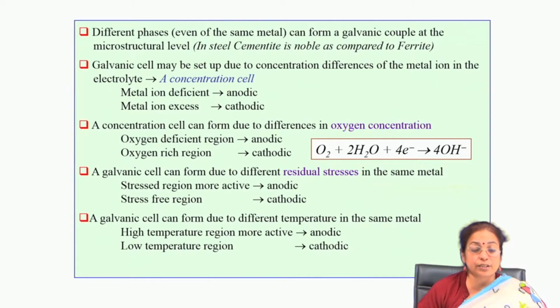For example, in case of pitting corrosion, the differential aeration cell formation is there because of oxygen concentration difference, which is nothing but a kind of galvanic attack. So, initiation starts because of the galvanic corrosion and then it proceeds to a large extent because of the autocatalytic reaction.